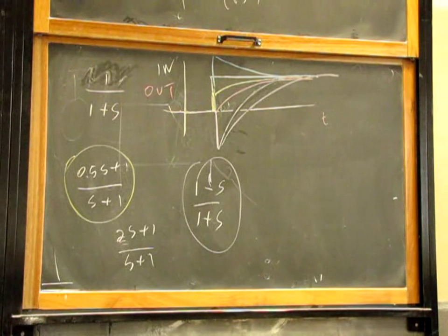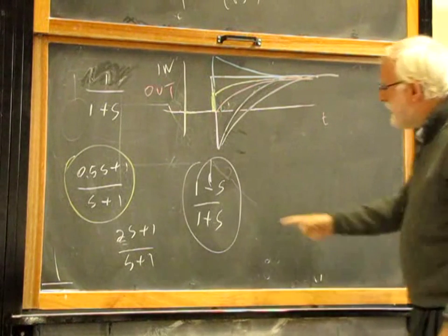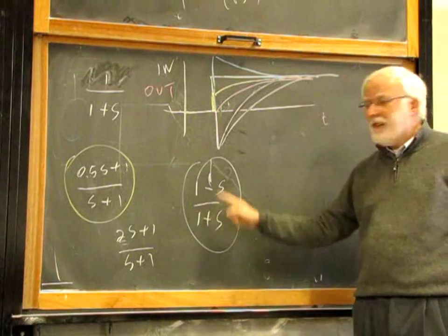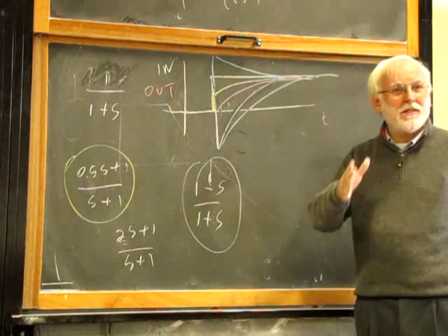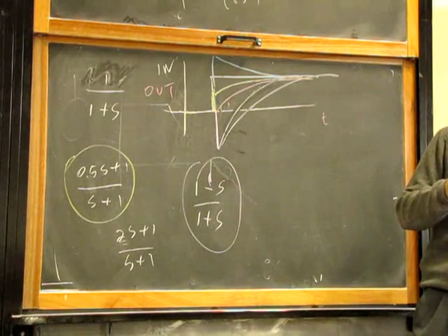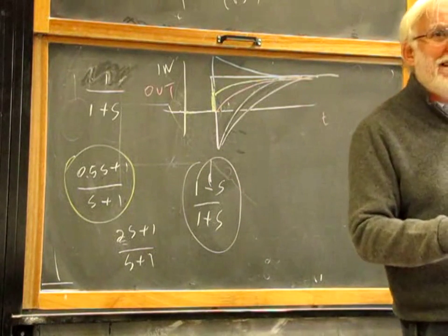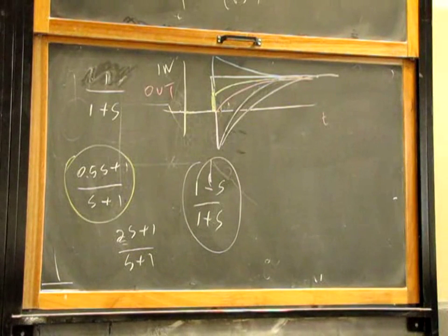What is the only way to drive a car like this? If you want to go to the left, you don't go abruptly to the left. You move slowly to the left. If you move slowly, it means that you don't have high frequency because you are going slowly, and so you get your DC gain. That means crossing over before the right half plane zero. You are lucky that cars are not like this, but airplanes are. In an airplane, you move the yoke to the left, the airplane banks to the left and goes to the right. That is not nice.